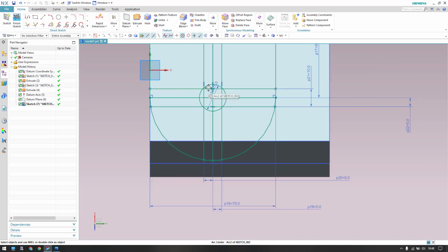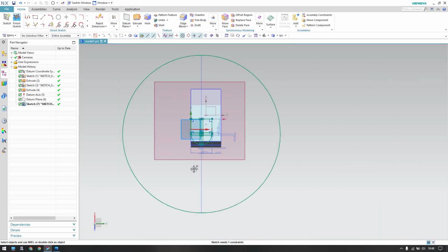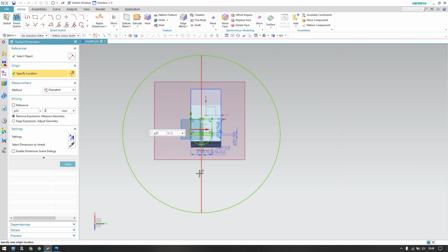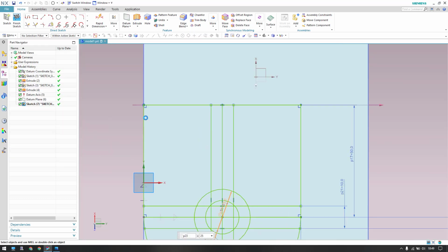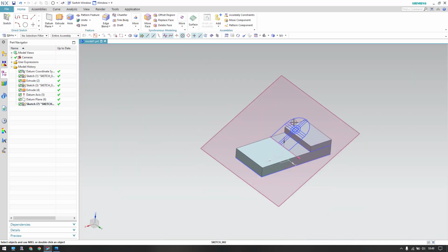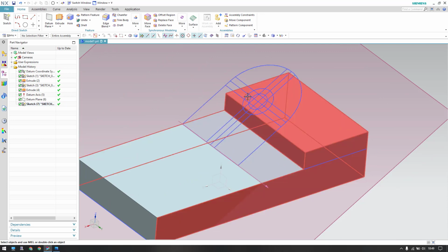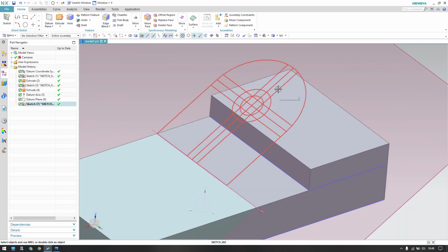And we also have one more circle here, so this dimension I assume as 25 mm. Oops. So it's too big, let's make it 25 mm. Okay, so now all the sketches are done, so let us finish this sketch. So now you can see here we have multiple lines, so we just need to make sure we are selecting proper curves in order to have extrude.